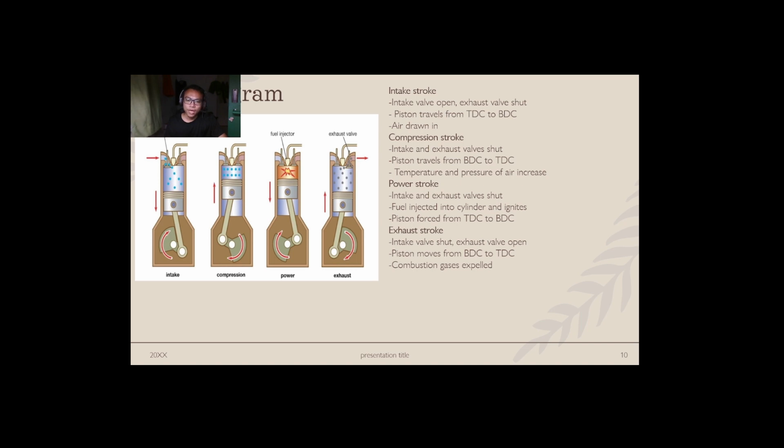And lastly is the exhaust stroke. The intake valve shuts and the exhaust valve will open. The piston will move from BDC to TDC, and the combustion gases will be expelled.